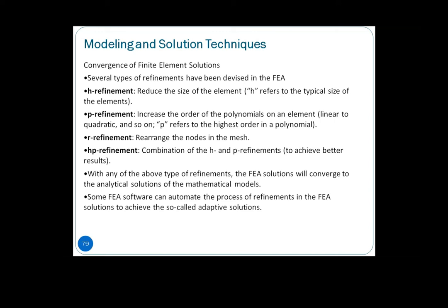In terms of the results, what we are doing here is we have to set a stopping criteria, the tolerance that we want to achieve. Then it helps us to refine the size until it achieves the tolerance requirement that we have set. So then you get at least a more reliable result. So in terms of manual types, adaptive is the more automated one.